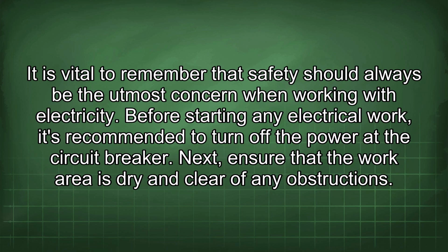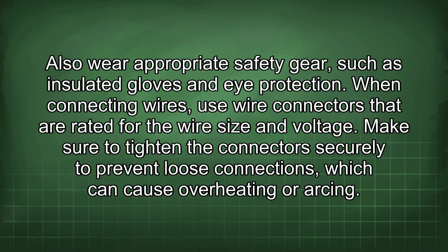It is vital to remember that safety should always be the utmost concern when working with electricity. Before starting any electrical work, it's recommended to turn off the power at the circuit breaker. Next, ensure that the work area is dry and clear of any obstructions. Also wear appropriate safety gear such as insulated gloves and eye protection.